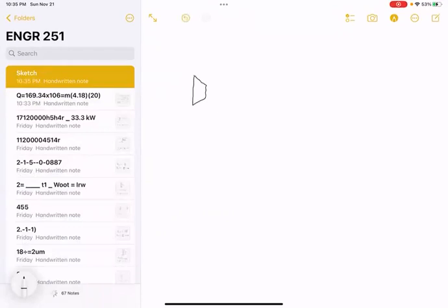So the air enters the engine. It goes through the compressor, and it goes from relatively low pressure to a relatively high pressure. And this process is an isentropic process for a Brayton cycle. In the ideal case, this is an isentropic process. So that's just something to bear in mind. And then the rest of the cycle is exactly the same as the Rankine cycle in that we have an isobaric heat addition. So this is where we have our Q in.